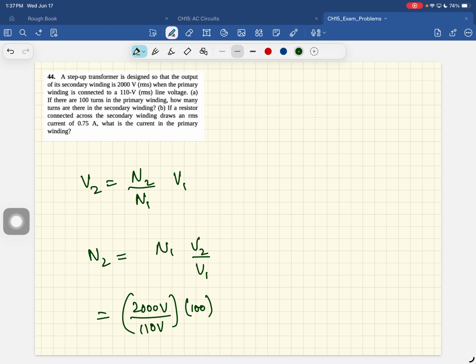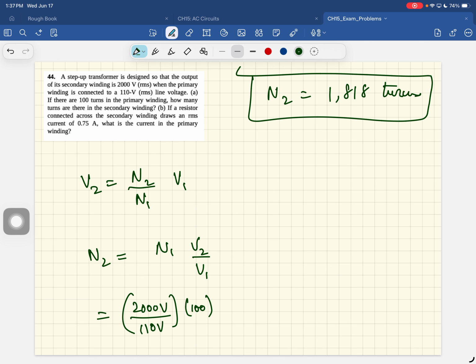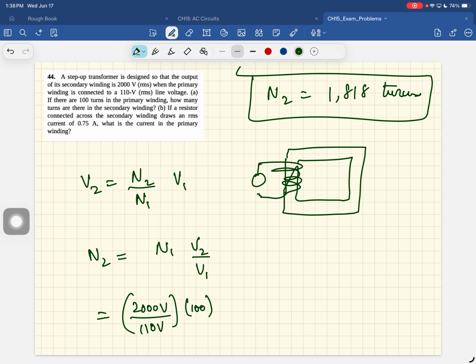So what is the RMS current in the primary coil? So, yeah, V in I in equal to V out I out. I in is V out over V in times I out. So 12 volts divided by 110 volts, and these are all RMS, times 4.17 amps.